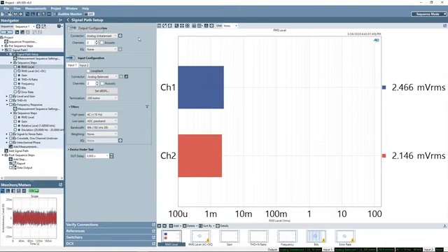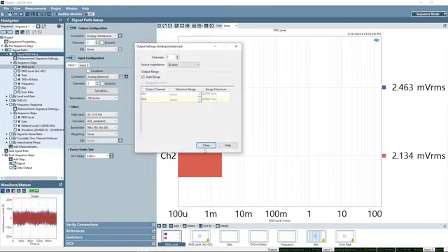The signal path setup is a special measurement with a collection of settings, controls, and results. Signal path setup is always the first measurement in every signal path. Here we have the output configuration, where you select the connector to be used. I'm using analog unbalanced 2 channels for my stereo amplifier, which is connected as the device under test in this video. Additional settings for the selected connector are accessed here.